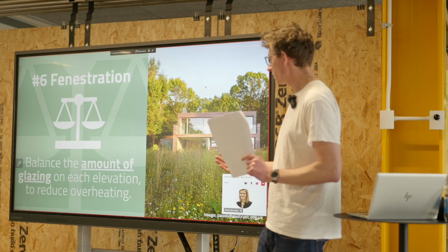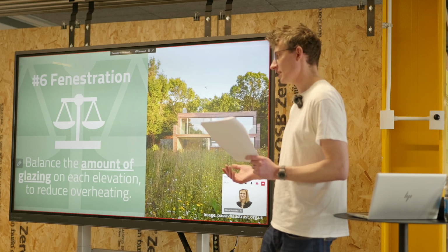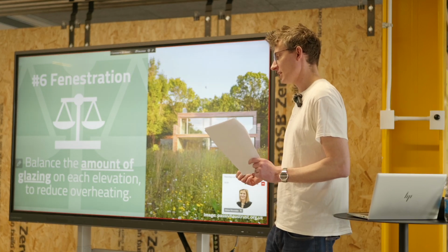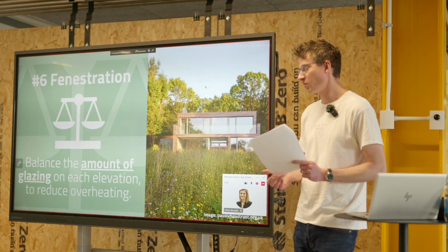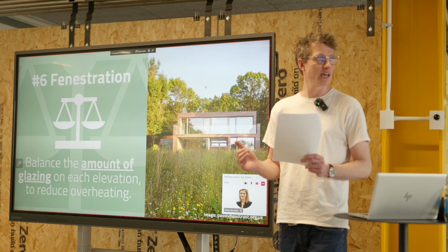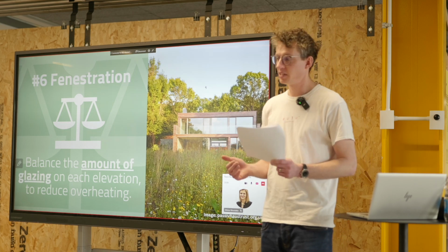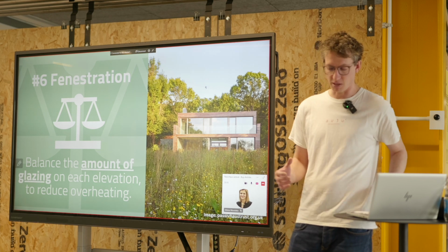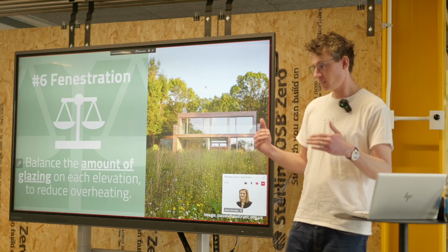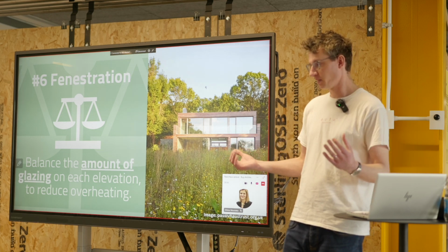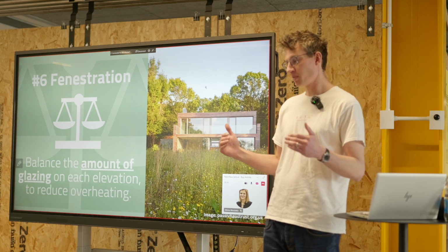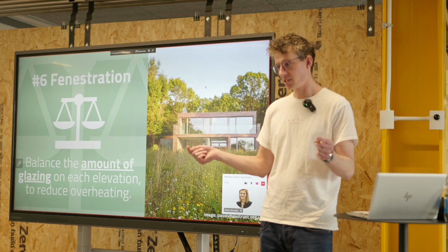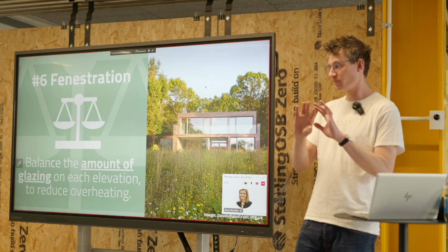Finally, on the fenestration, a really important way of making windows more effective is by positioning them in the right place. You see this all the time, and I'll show you an image in a few minutes of an unsuccessful window, but quite often windows aren't positioned in the right place. Let's think about a traditional wall where you've got perhaps brick on the outside, block on the inside, and insulation in the middle. Historically windows have been positioned either in the brick or in the block, and that creates huge cold bridge issues around the edge of the windows.